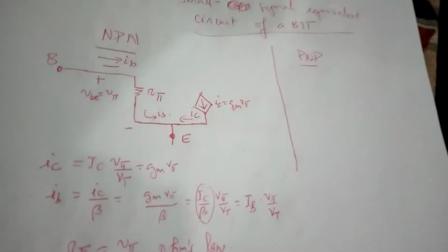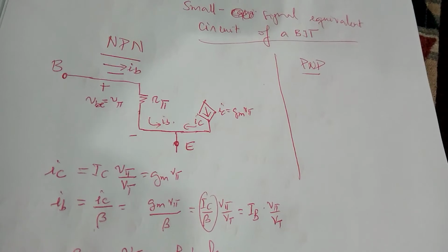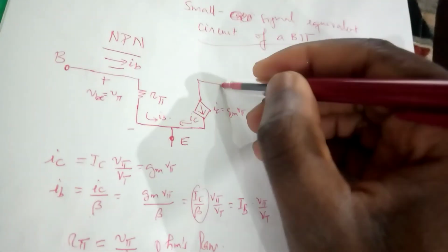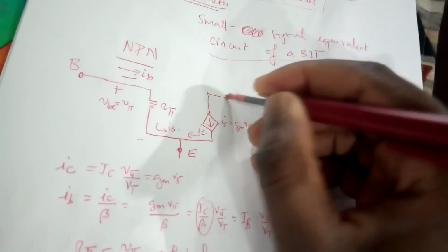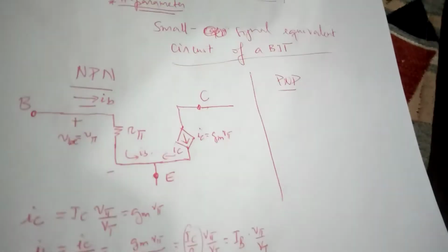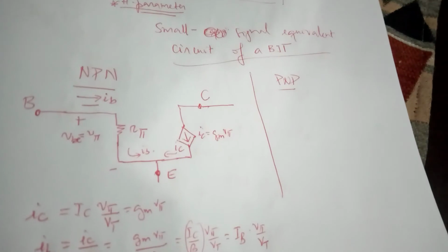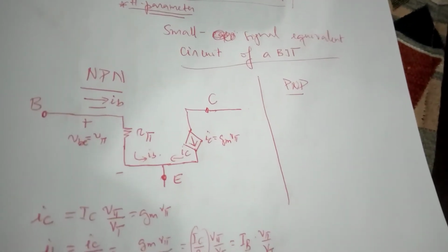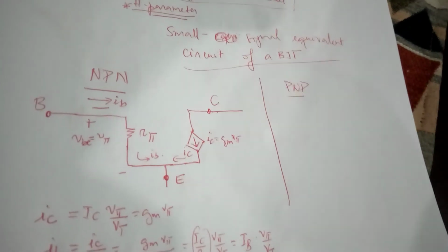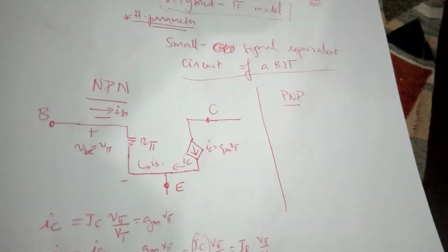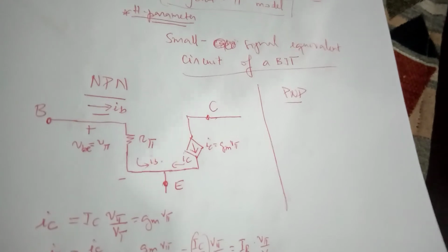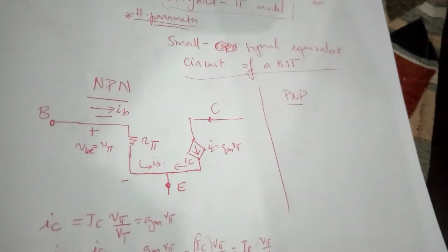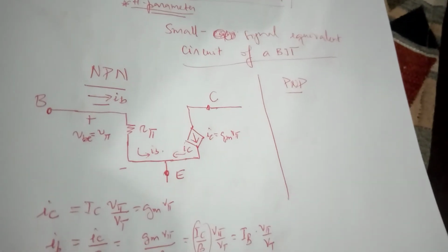And here I'm talking now about the AC collector current, and that goes to the collector like that. So the collector side is represented by a current source. Why? Because inherently in a transistor, as we said, it's a transconductance amplifier by default. So you apply VBE, you get IC. So you can still convert the IC into a voltage for you to get voltage to voltage, but naturally it's first VBE generating current.